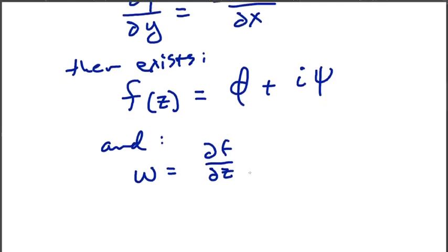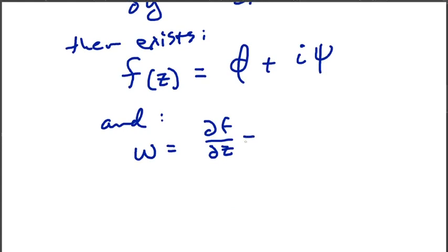The w is a complex velocity, and the components of this complex velocity are u minus i times v. u here is the x component of the u vector. v is the y component of the u vector. And there will be times where this complex velocity is a very powerful tool for solving flow, especially around objects like cylinders. It can be a very compact way of representing your overall flow.